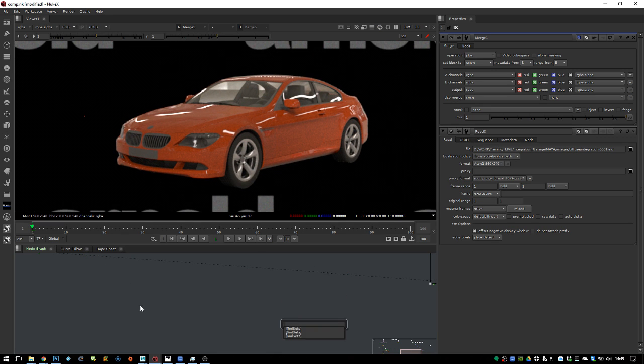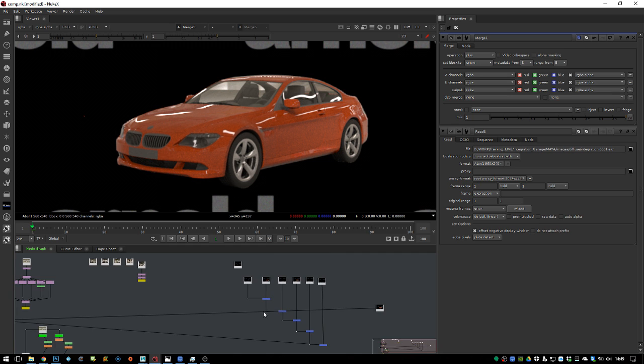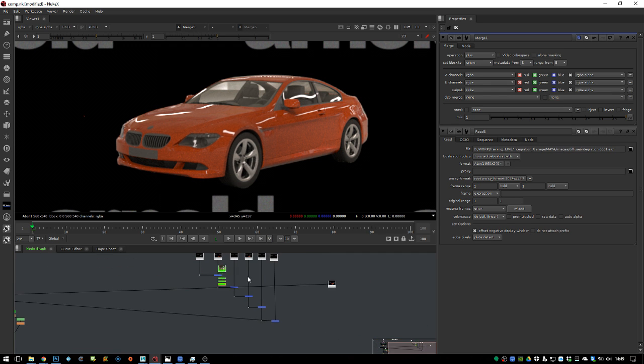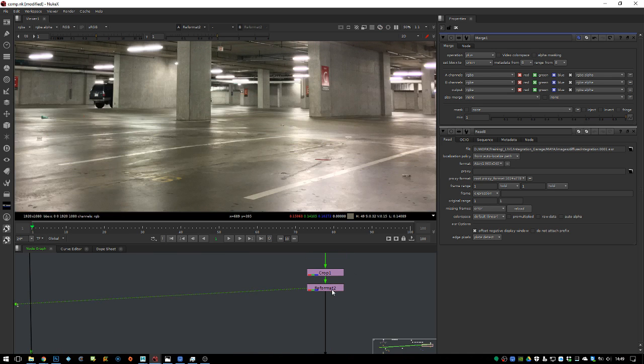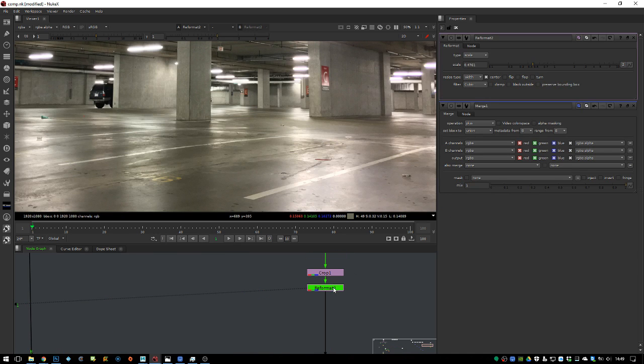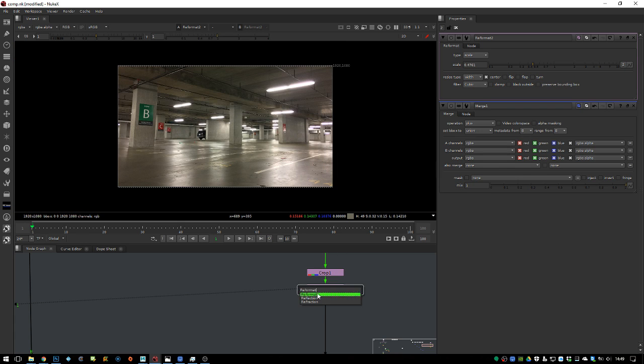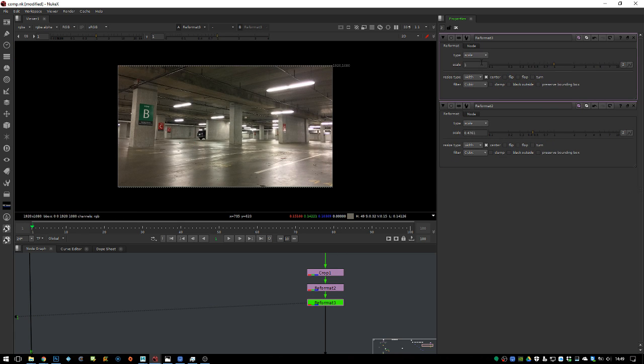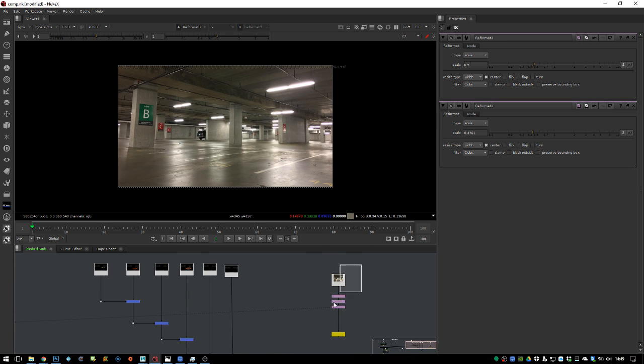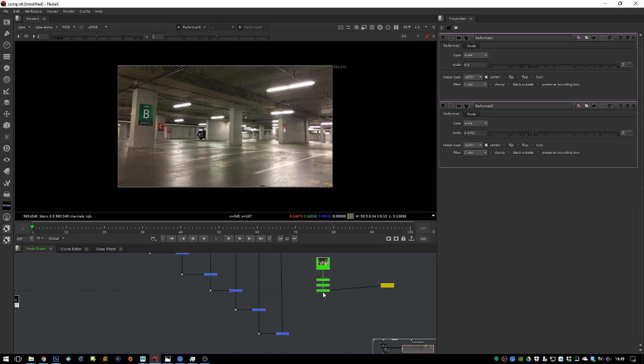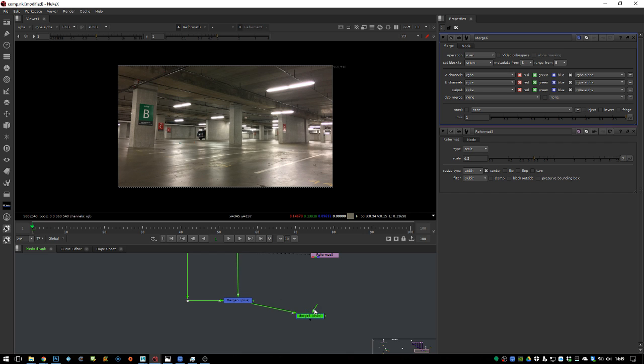Okay, so that's what we got, and then we need to reformat. I think we use this plate, and we rendered in a half HD. So this is now I think 1920. Yeah, and we just reformat this again and we scale it by 0.5. We should get half HD. No, I did not merge it into one EXR, so I did not use the shuffle node. I'm not sure how you can set this up in batch rendering. Not sure. Which is also not that of an issue.